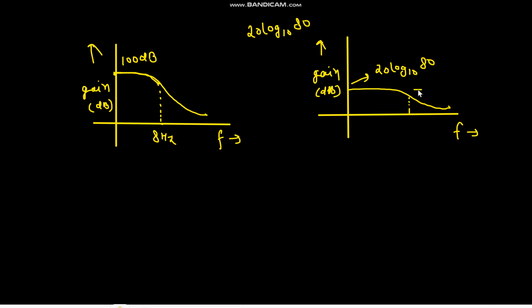Okay, and at 3 dB lesser, this is 10 kilohertz, because that's what we call bandwidth or cutoff frequency, right? The gain that we have at zero frequency and the gain that is 3 dB lesser, the difference between those two frequencies is the 3 dB bandwidth, right? So now you have to find the gain at 15 kilohertz, that would be somewhere here, right? Here you can find the gain, so that you need to find.